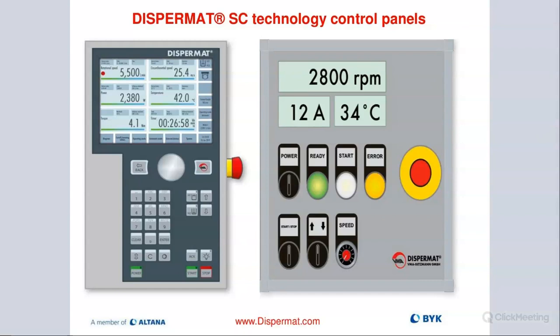which can be really helpful because it's actually an indirect measurement of your viscosity during the dispersion process. And a lot of customers really benefit from that, to see what is happening to my dispersion during the dispersing and milling process. We can see the tip speed displayed on the top right. We have a temperature readout as well as a timer function.